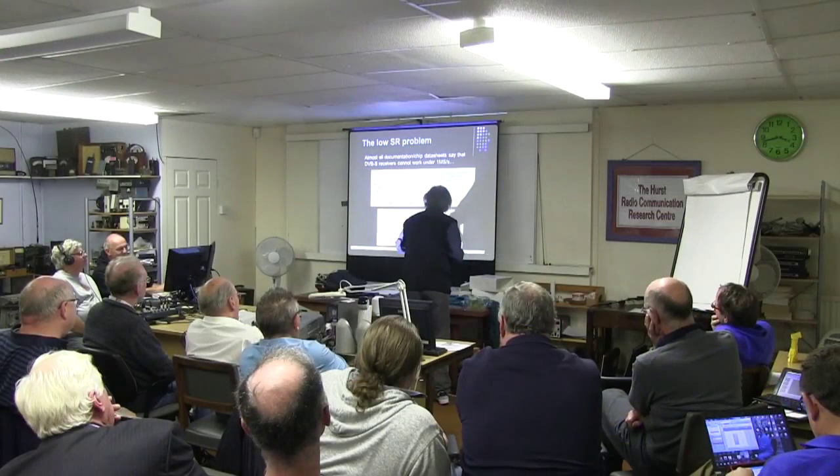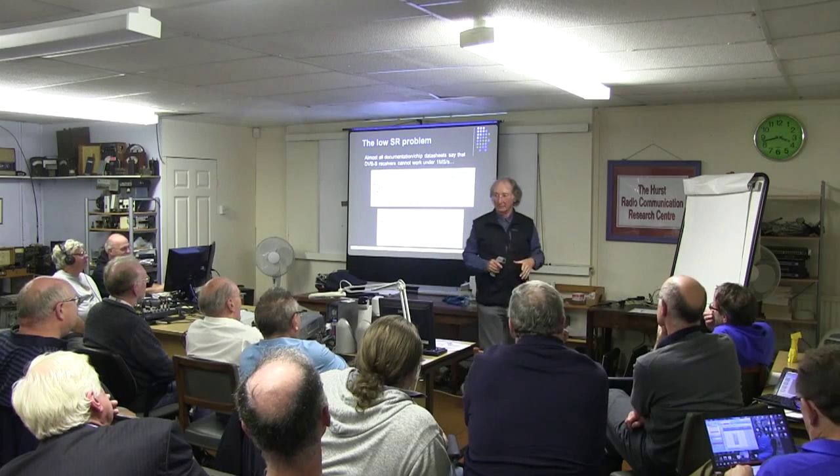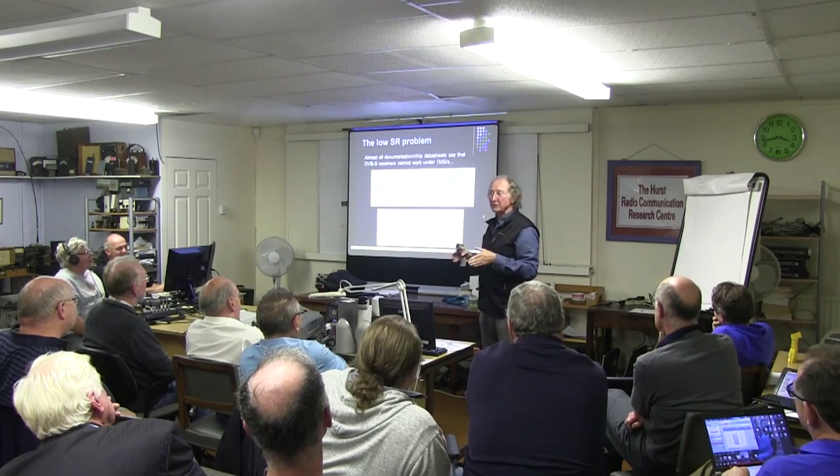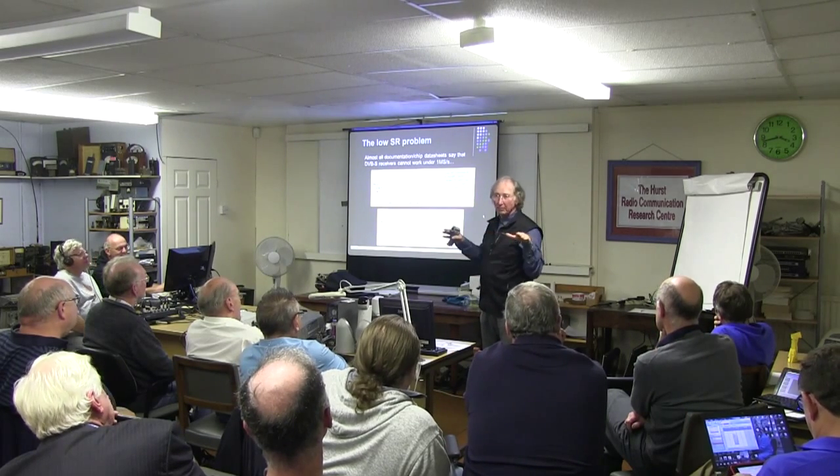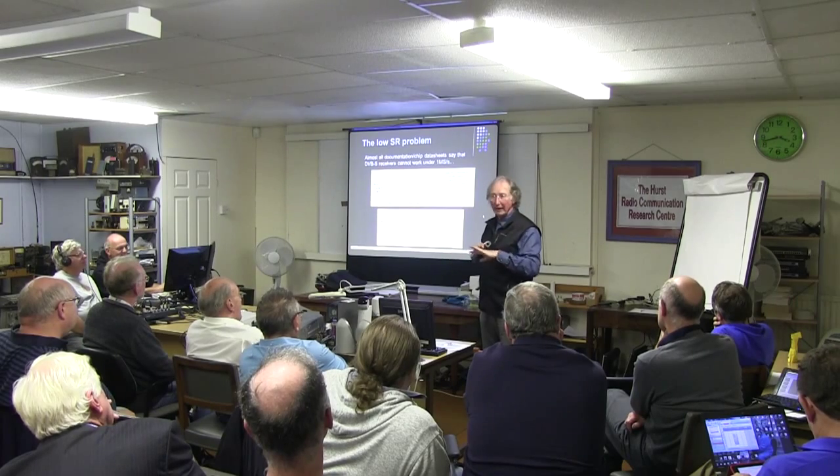So, I suppose I have a receiver, a set-top box, that can receive down to 600 kilosymbol. At 600 kilosymbol, it stops receiving. If I go lower, I cannot receive anything.